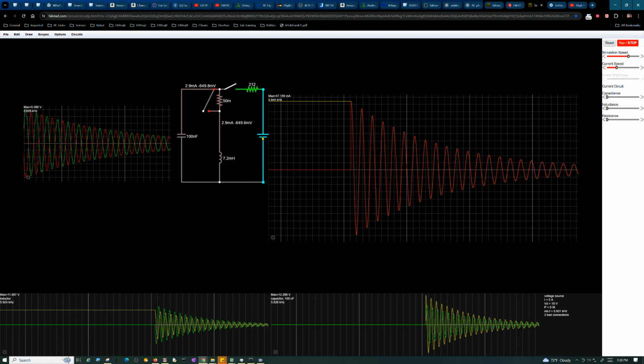Now this thing's predicting, and maybe I should try actually setting it to the same parameters. I guess I can try that real quick. But the problem is I've got my power supply in constant current mode to do this, so this is just the most convenient thing. But at any rate, it's predicting, as you can see down here, that for 10 volt output, I'm getting a peak of about 12 volts, and that's about 24 volts peak to peak.